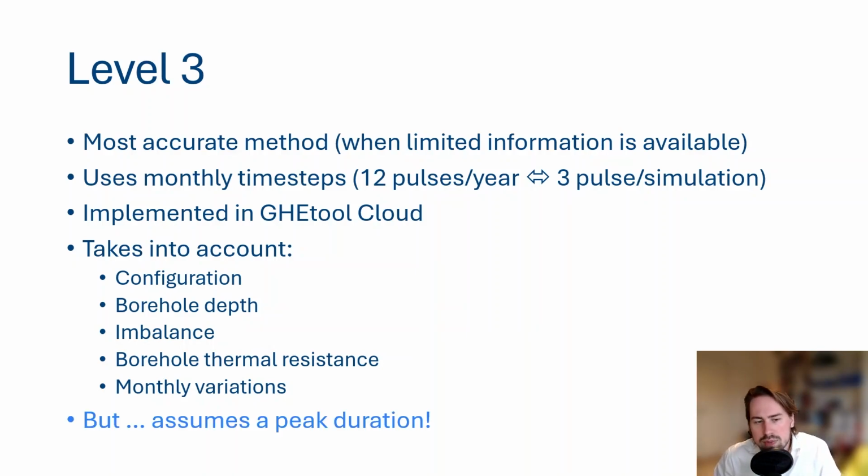One disadvantage of this method is that we still need to assume a peak duration, a duration of our peak power, because we're working on a monthly time scale. We do not know exactly how long the peak power lasts, so we need to make an assumption for that.